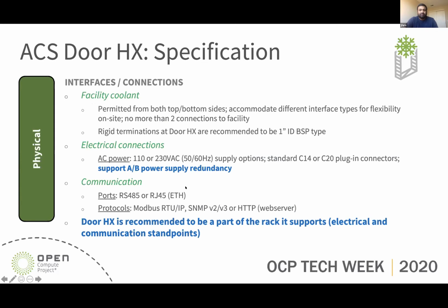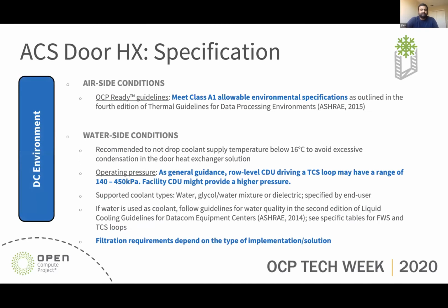Once again, calling out the harmonization efforts with regards to ensuring that AB power supply redundancy is put in place, as would potentially be the case on the rack side with the IT gear. And to go along with that, a recommendation from the community in general has been that the door heat exchanger is recommended to be a part of the rack that it supports, both from an electrical and communication standpoint. From an environmental standpoint, we divide this into airside and waterside conditions to be able to scan across